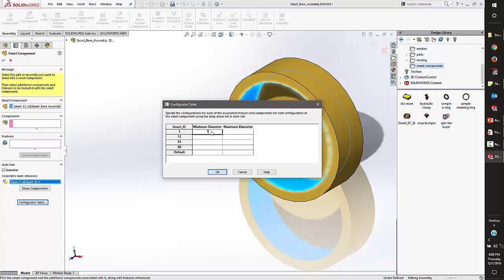So I'm going to say that a 1-inch one will fit between a 1.3 diameter and a 1.4. The half-inch diameter will work with a 0.8. I don't know what these, I think it's half-inch, but we'll see. So it's 0.8 to 0.9. And, unlike our coincident mates, this is the fuzz factor.